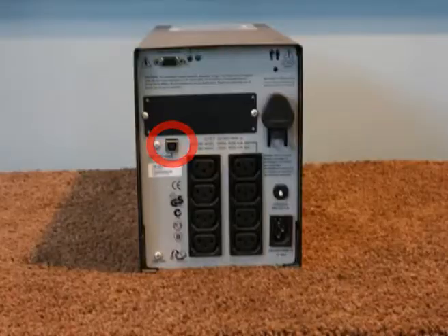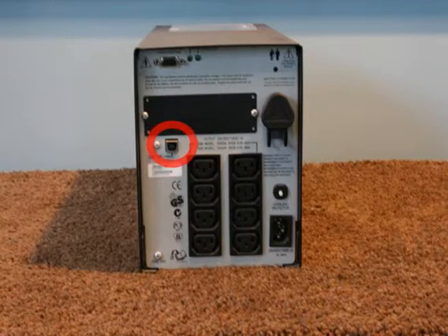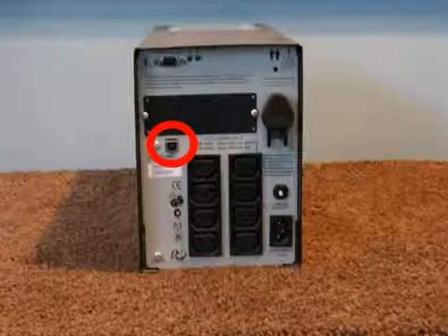These days, a modern UPS also comes with a USB connection to the main desktop. Using the USB interconnection, the desktop can know how much battery power is remaining and for how much time the desktop can sustain on this battery. The moment the UPS is unable to supply the power, the desktop recognizes that and automatically starts the shutdown process.